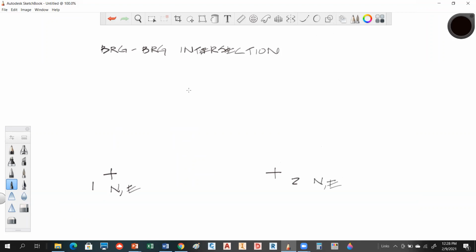So you have a point out here. Let's just say it's a manhole, and we don't know what its coordinates are. So we could shoot a distance and get a direction. We could do a direct routine, but direct routines don't always work for different reasons, obstructions or something maybe. But if you sat at 2 and measured a direction to that point, and you set at 1 and measured a direction to that point,